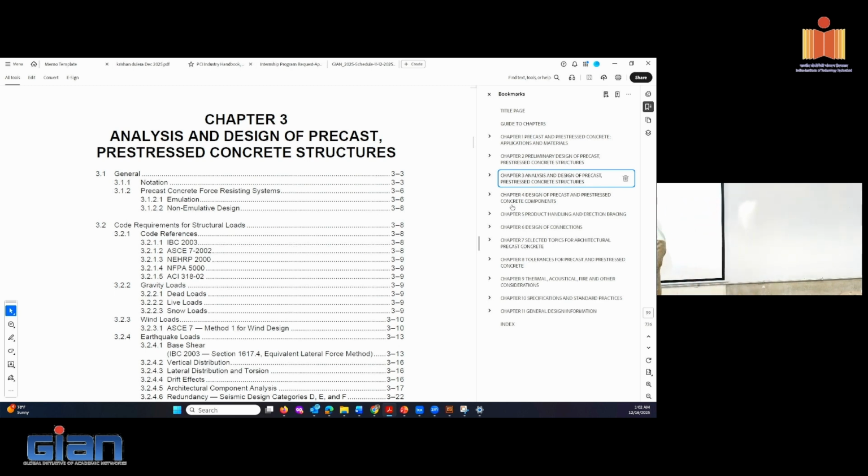These two, the NEHRP 2000 and NFPA, in some areas or regions, may be adopted instead of IBC. The NEHRP provisions basically eventually go into IBC. So if you want to follow what the upcoming changes are, you can possibly use the NEHRP provisions. NFPA is another organization that put out a design code. Again, for political reasons, they couldn't agree with each other and they published their own code. If a region chose to use it, then they had to do accordingly. These talk about dead, live, and snow loads.